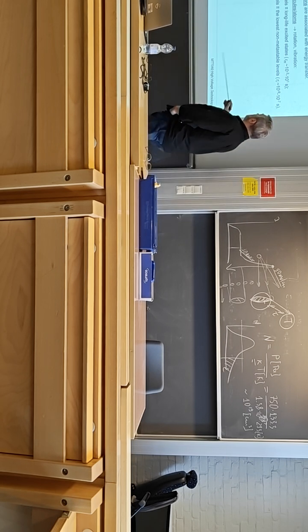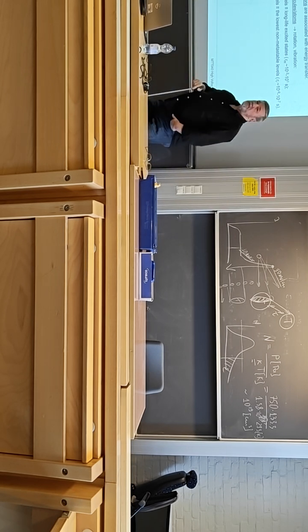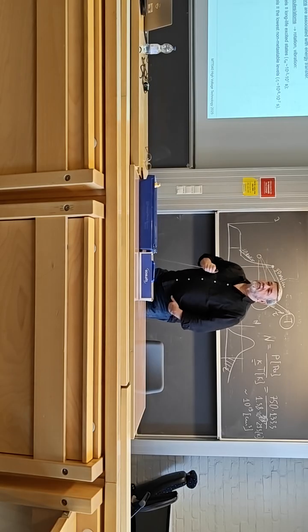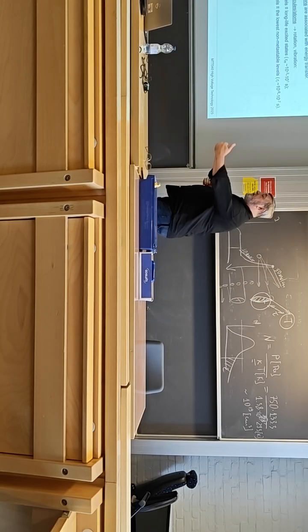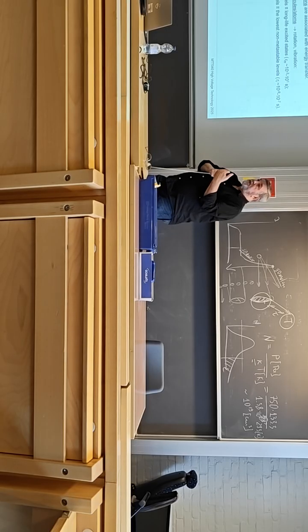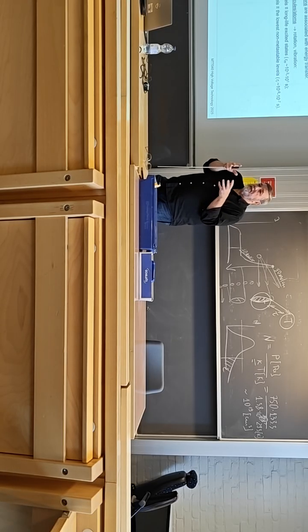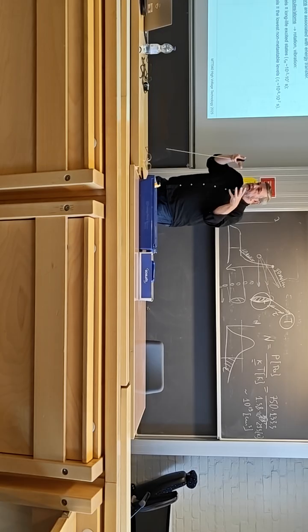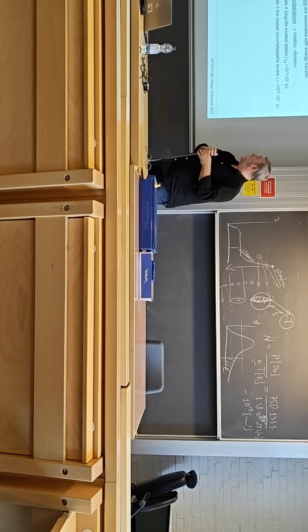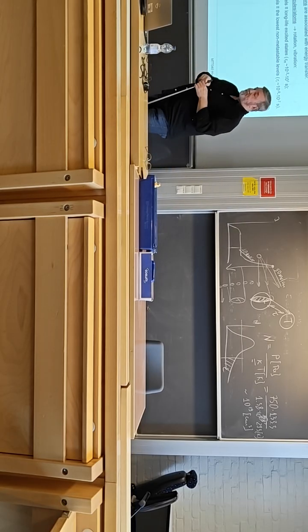This is very important for the probability of breakdown, because if it's a metastable state, then the next electron coming can ionize it and needs lower energy than the original one, because it's already excited. So the electrons are on a higher level and less strongly connected to the nuclei. So that's the difference.